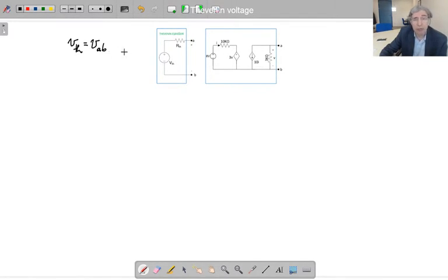So because of that rule, the problem becomes calculating one of the element voltages. If you want to apply the classical methods that we have seen already, what are they? The mesh current method, the node voltage method. These methods are for finding all the elements' currents and voltages. Now what we require in this case is just one element voltage, and this element voltage is going to be my Thevenin voltage. Therefore, no need to apply the mesh current or node voltage method here. Since the circuit is simple, we could do it manually, without any method. We can just use our mind. So let's do it then.